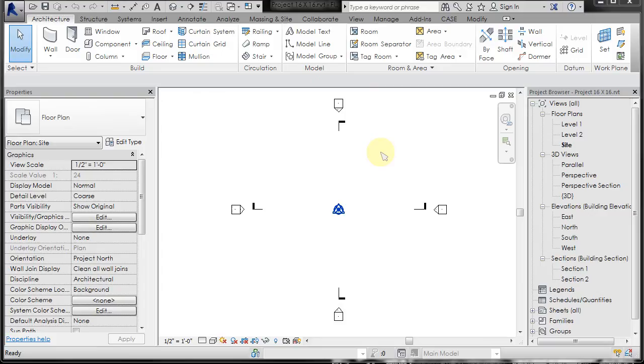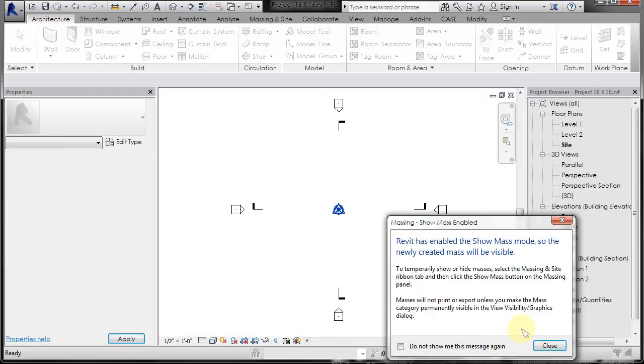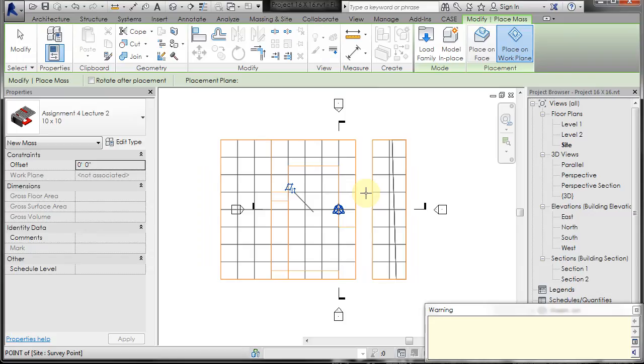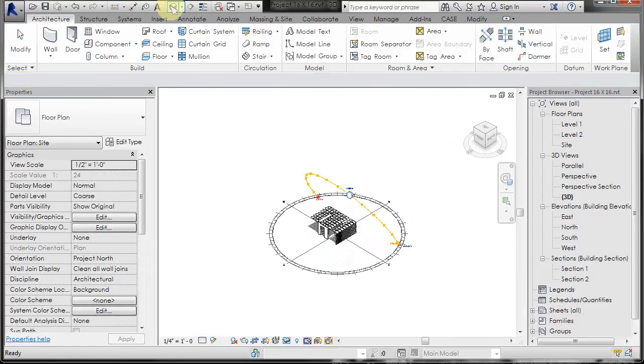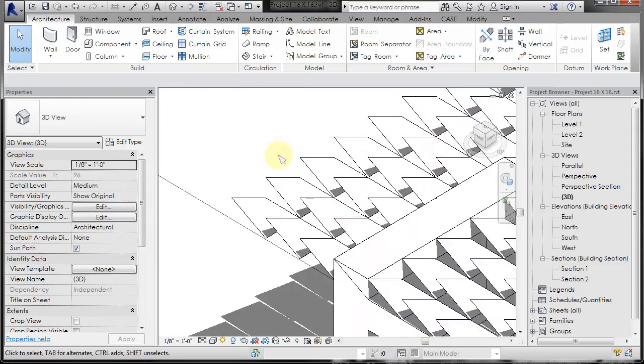Alright, so that project is open. I'm going to Control Tab back to my conceptual mass and load that into the project. Place that, escape, ignore the warnings, go to our 3D file. Now, while you're documenting this in the project, you may want to get some thickness in here. It's nice to have surfaces when you're testing things because they take up a lot less memory.